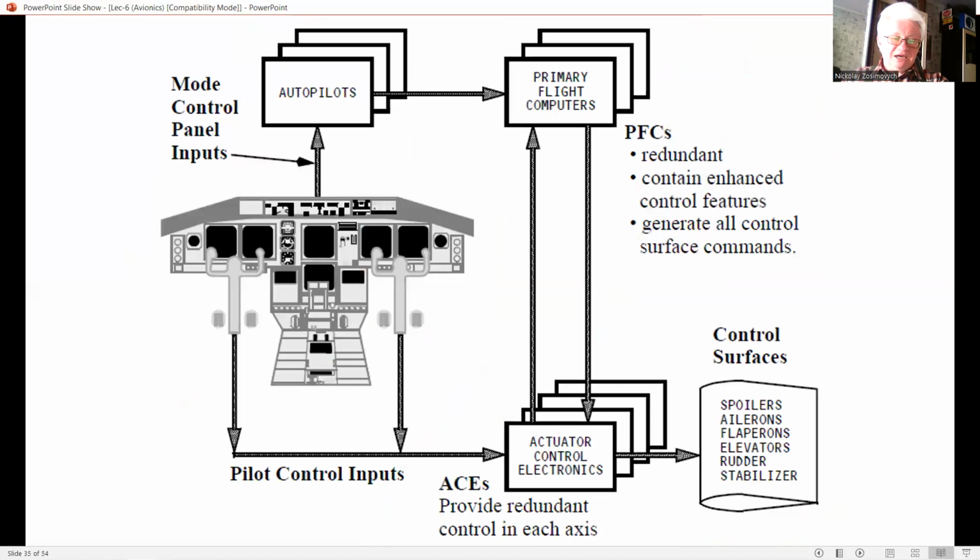It should be noted that the statistical level of safety currently being achieved with civil transport aircraft corresponds to a figure of around 10 to the power of minus 6 per hour. And this figure is derived from the total number of civil aircraft crashes occurring in a year from all causes divided by the total number of aircraft flying and their annual operating hours.